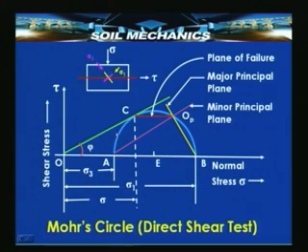You know that in a Mohr circle, point A corresponds to the minor principal stress, point B corresponds to the major principal stress, and the point OP, which is obtained by drawing a line parallel to the plane of sigma 1, gives the pole OP, because by definition the pole is a point on the Mohr circle which has coordinates sigma and tau equal to those on a plane passing through that OP and the point A.